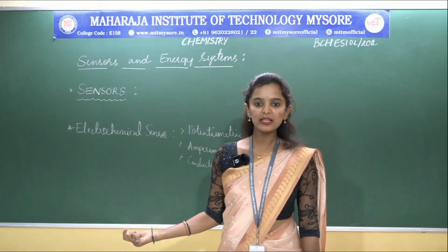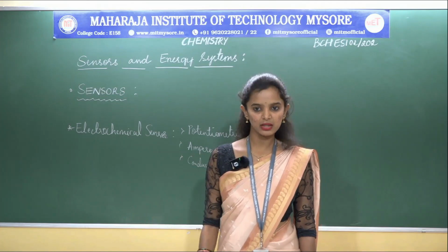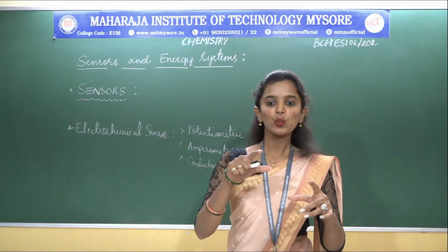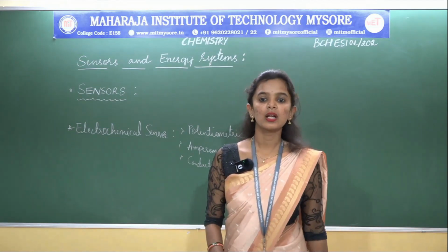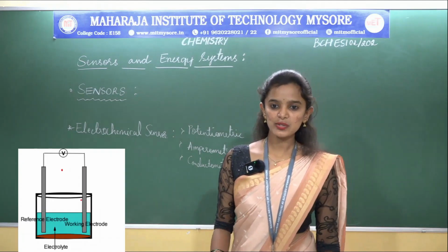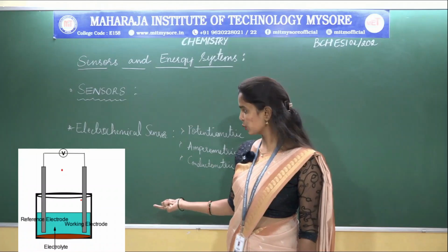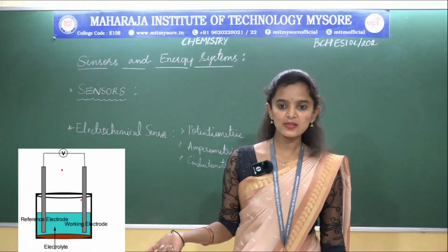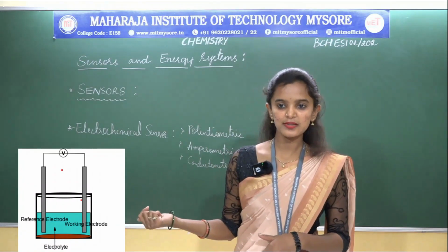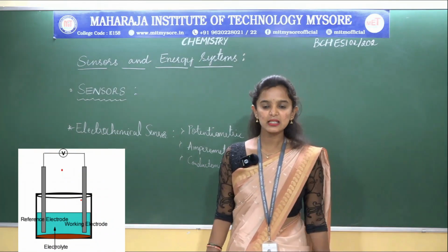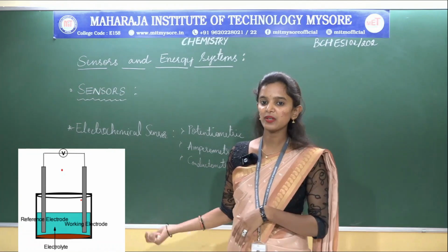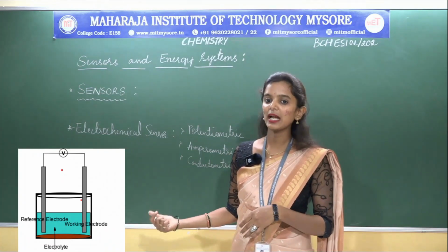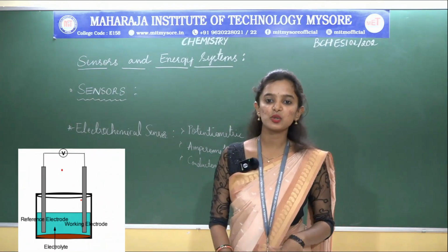Electrochemical sensor always requires a closed circuit. Current must flow within the circuit to make a measurement. Since we need a closed loop, at least 2 electrodes are necessary in this electrochemical sensor. These sensors are often called electrochemical sensors because of the presence of electrodes and the change in potential which could be observed.